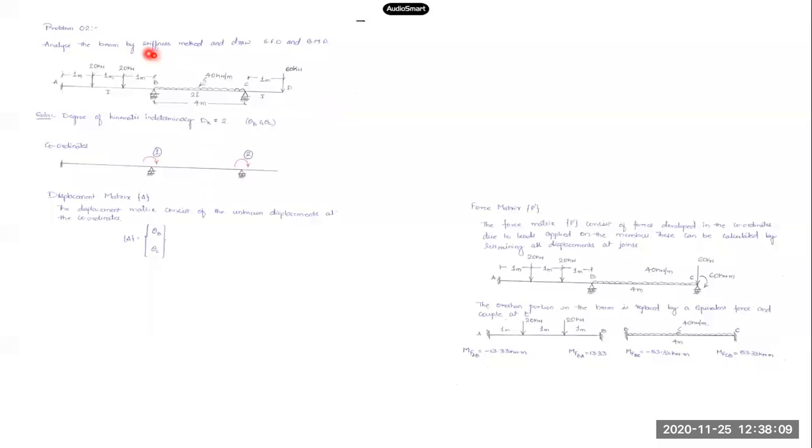So this entire beam can also be represented in this form. I removed the overhang portion over here. Instead of that, an equivalent force and couple has been placed at C. The 60 is due to 60 into 1 meter, 60 kilonewton meter, with clockwise direction. And this force will shift as it is, in downward direction over C. This is the simplified form of this beam. I just removed that overhang portion, and whatever forces or moment it was producing at joint C have been applied here.